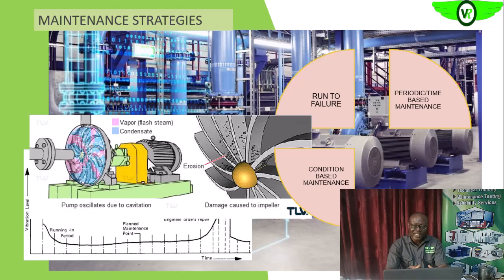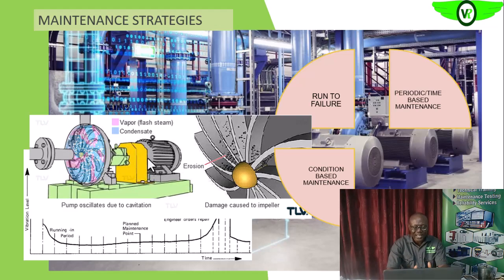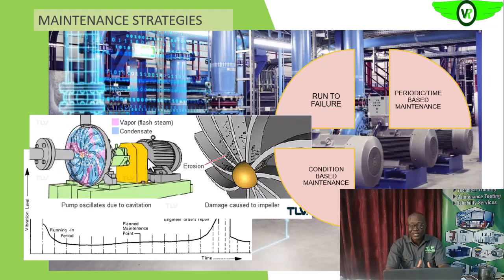And even the effectiveness of the lubricant in the bearing will be affected. So all of this can give us an idea as to the condition of the bearing, that's the bearing temperature. We can also be looking at vibration, as we'll see later. Okay, it's another parameter that we can be monitoring to give us an idea.